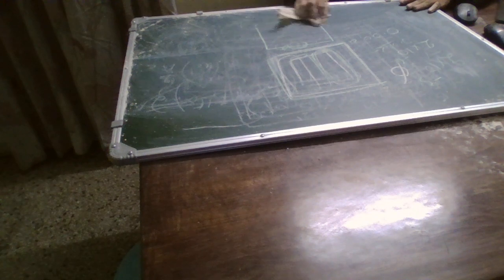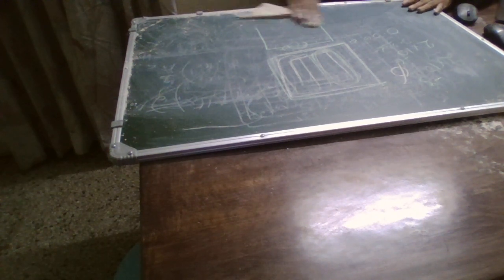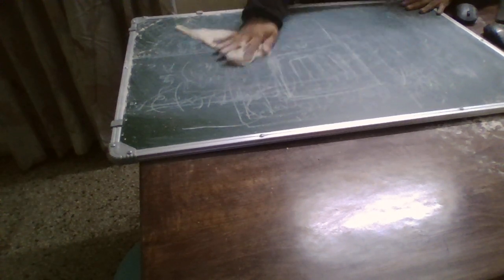Now let's go to the second material, the powder material. In the powder material we can have a powdered molypermalloy, and we can also have powdered iron materials. They are die pressed into toroids, EE cores and slugs. So the powdered core process also makes use of ingots.